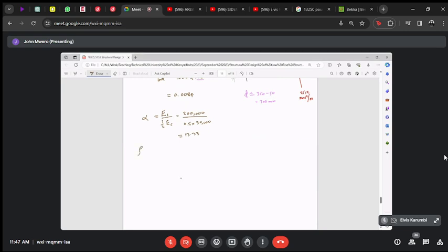So then we can calculate rho alpha. Rho alpha is simply 13.33 multiplied by 0.0084, and this, if my working is correct, should be 0.112. Therefore, the depth of the neutral axis for this section will be the effective depth, d, times minus 0.112 plus the square root of 0.112 squared plus 2 times 0.112, close all this in brackets.